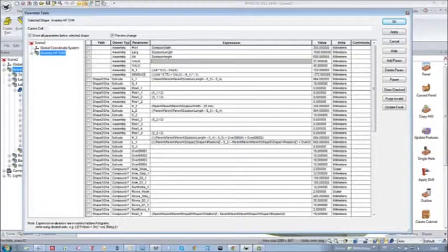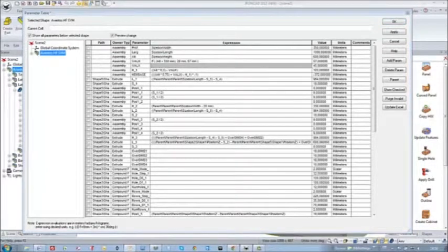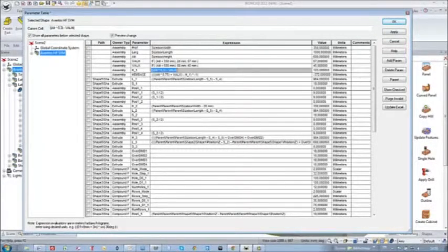At this stage, the hardware is still not parametric, because remember that its position is relative to the cabinet height. So I will need to introduce a function like if, then, else. I'm going to write something like: if the cabinet's height is above such a value, then my variable should be set to a certain value, and so on. I'm going to write it like we do in many applications, also in Excel for example. So this is the way I'm going to do this.